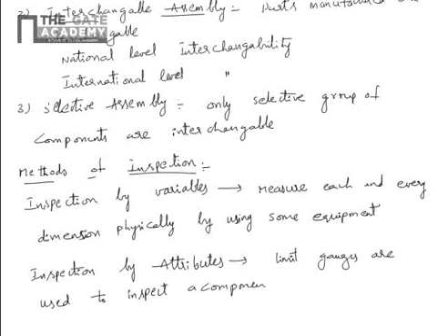So what are these limit gauges? For example, if you want to inspect a shaft, then you have to take a ring gauge, which has the opposite dimension to the shaft, that means it is hole shaped. You insert the shaft into that gauge.